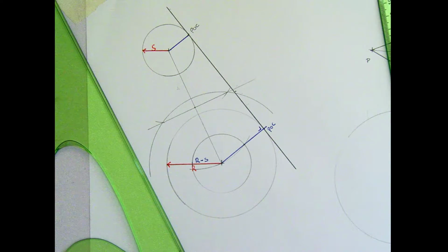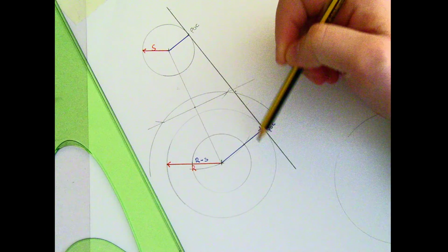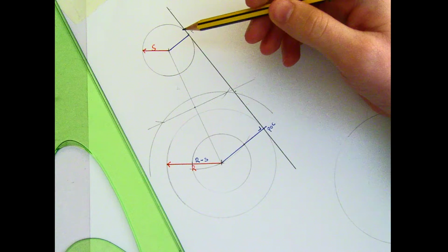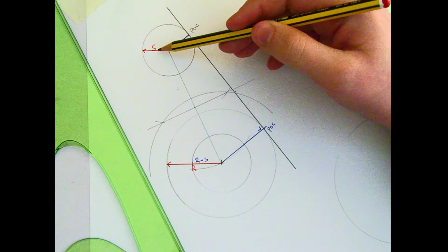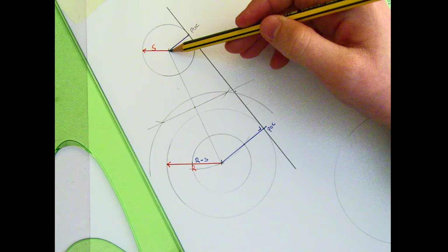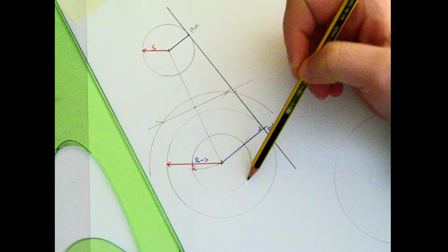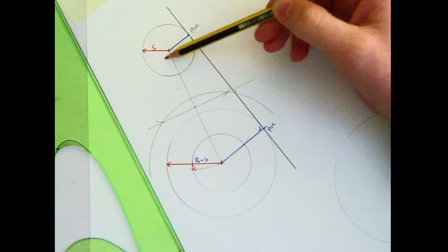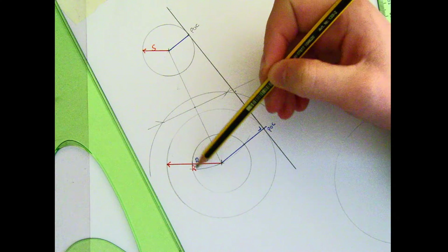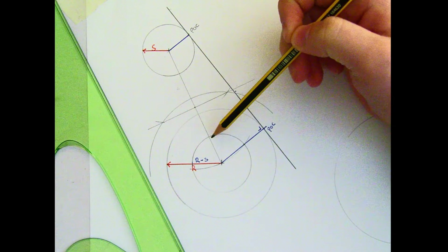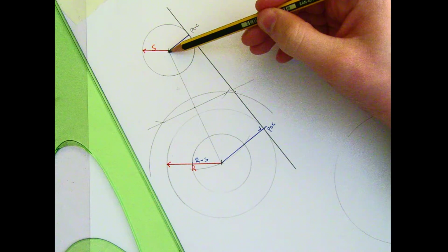So, quick recap on what we've done. We started with a small circle, and I had another large circle. I needed to reduce the small one down to a point, which I've done. So when I remove the radius off this one, I need to remove the same size of radius off the large one, so I'm left with a circle that is this big. So take S, minus it off this radius, so I must start from the outside and work in, left with this one. Now I have a point where I can draw a tangent from a point to a circle,